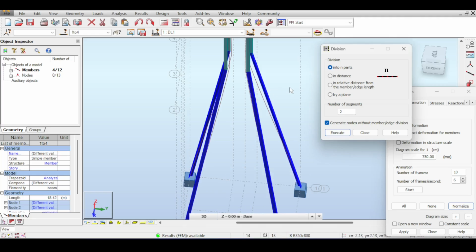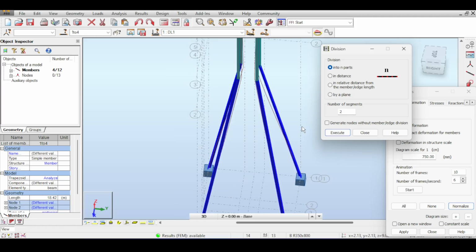So the first thing I should do before I split anything into 7 pieces is to split my bars into 2 pieces and enforce member division because I want to force this to be split into 2 pieces. So this is something I forgot about and realized while I'm modeling. I'm not going to video edit this because I wanted to see how somebody gets to a sudden realization that something is amiss. Because catching yourself making a mistake and rationalizing about how to avoid it is much better than me just taking a video and telling you here is how it's done.